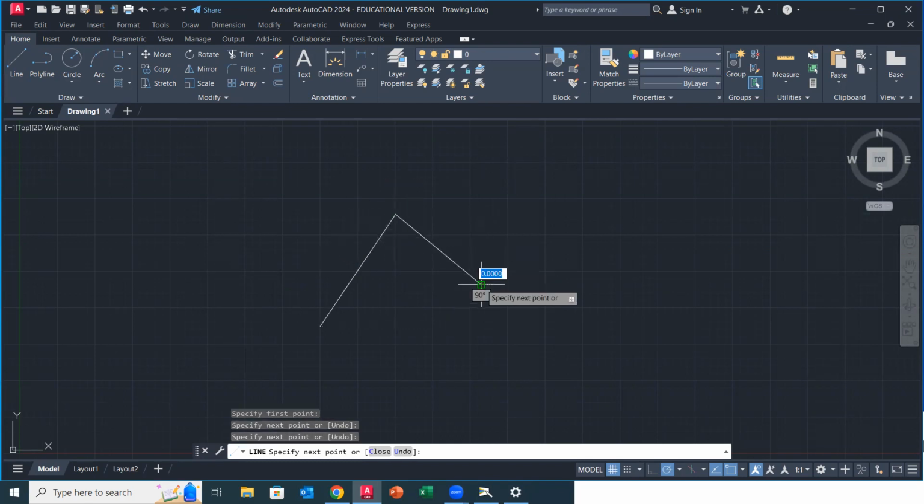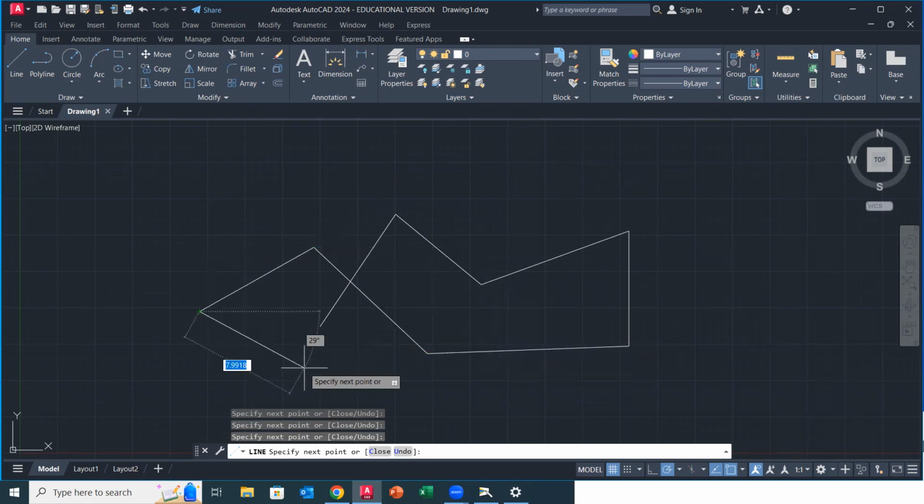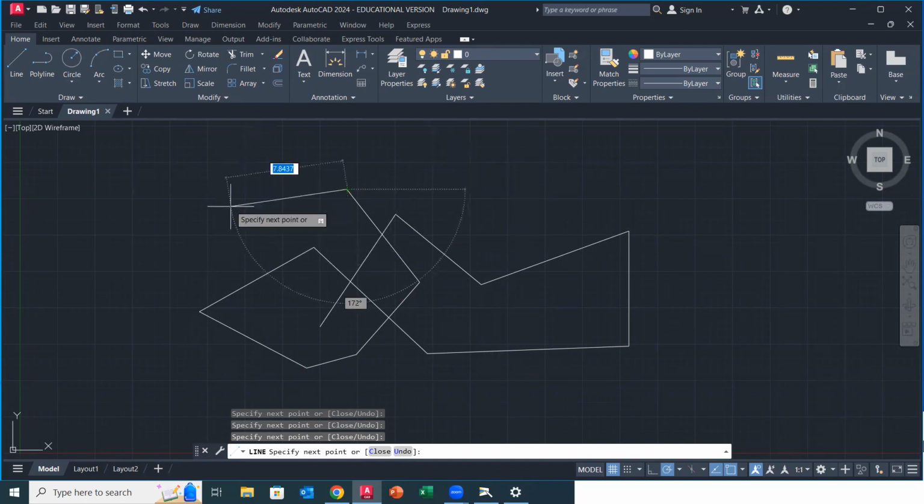So we can continue to left click, and you can just make a cool design. Now this isn't very accurate, as you can imagine, but it gets us laying down the points. Now, if I want to end this command, I have one of two things I can do. I can hit the escape key, or I can hit enter. Enter confirms I'm done, or the escape key says I'm done. If you're ever in trouble, escape key.